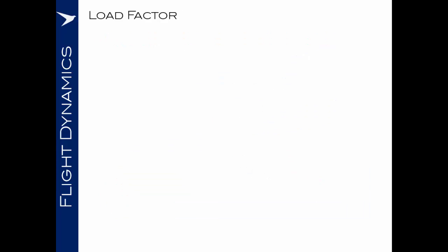So let's move on to a discussion about load factor. But what is load factor? It is a measure of the acceleration being experienced by the aeroplane. Importantly, whilst we often think about load factor in terms of a force which is forcing us into our seat or out of our seat in the vertical plane, load factor can be across any dimension.